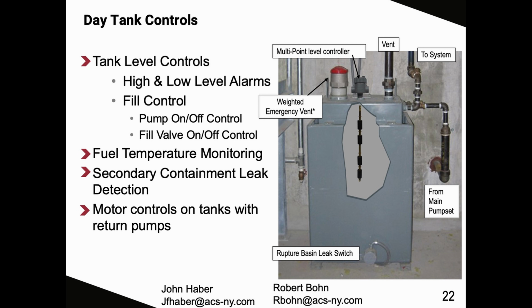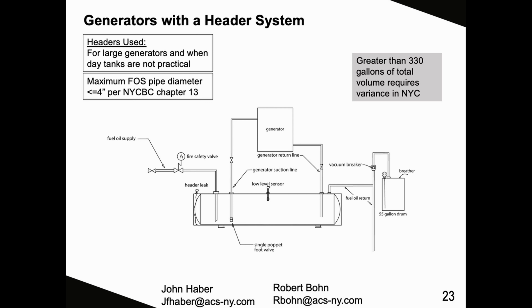Same holds true for UL tanks. So you're going to have a 5 psi rated UL day tank that would have a fitting on it, the large fitting. You're going to combine your vent lines to match that larger fitting, and then the vent line itself has to be sized according to the run, and keep the back pressure on that day tank below the 5 psi. Right, right.